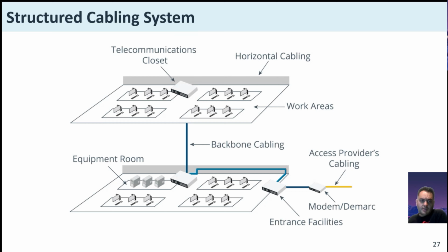Horizontal cabling is so called because it typically consists of cabling for a single floor, and so is made up of cables running horizontally through the walls or through the ducts or ceiling spaces. In most instances, if you have a building that doesn't have any crawl spaces or you can't get into the walls, because the sheetrock is already laid down and it's not a new development, you can run cable hiders, plastic molding. And of course, you'll see the horizontal up and down, left and right.